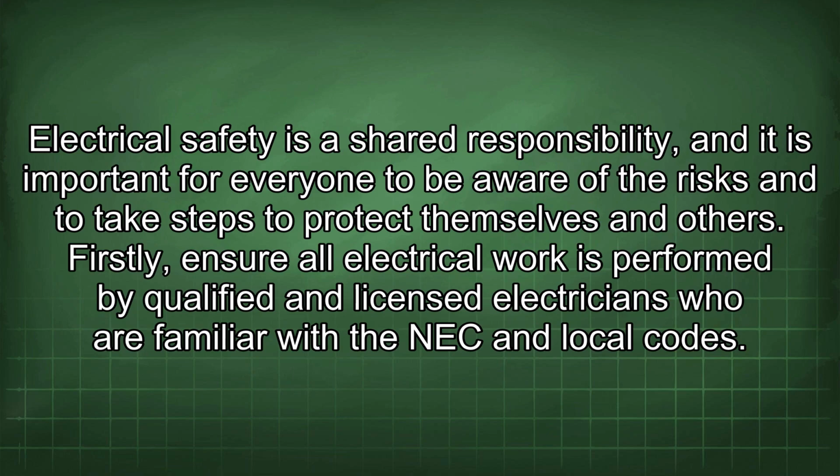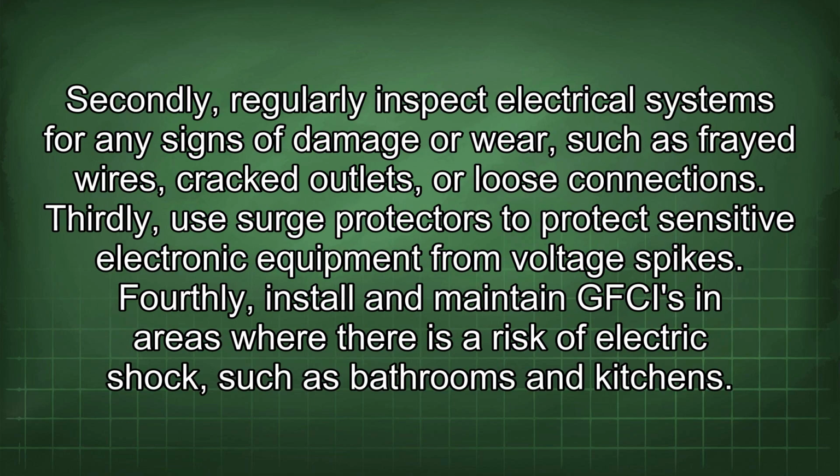Electrical safety is a shared responsibility, and it is important for everyone to be aware of the risks and to take steps to protect themselves and others. Firstly, ensure all electrical work is performed by qualified and licensed electricians who are familiar with the NEC and local codes. Secondly, regularly inspect electrical systems for any signs of damage or wear, such as frayed wires, cracked outlets, or loose connections. Thirdly, use surge protectors to protect sensitive electronic equipment from voltage spikes.